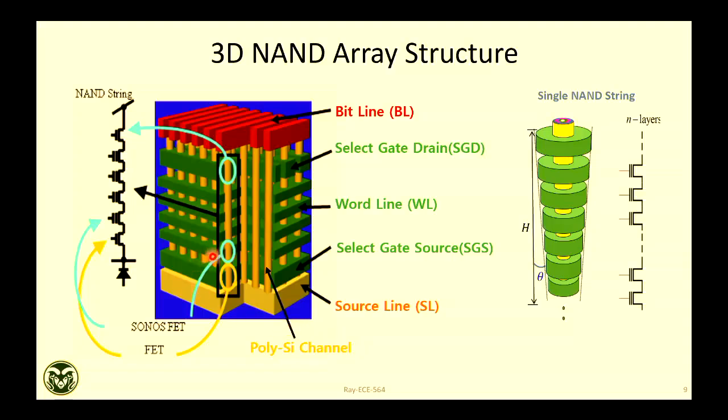You cannot do it here because the moment you go to 1000 degrees centigrade, everything will be messed up. All your layers will be melted together. So temperature is critical here. At 200 degrees centigrade, you cannot have crystalline silicon. You can make vapor of silicon and grow it layer by layer, and that's why the quality of silicon is poor. Because crystalline silicon has high mobility and good quality, but polysilicon has less mobility. So your sensing current will be limited, low. So those are the issues in 3D NAND.